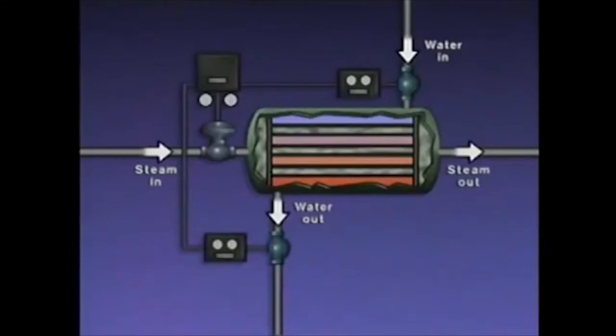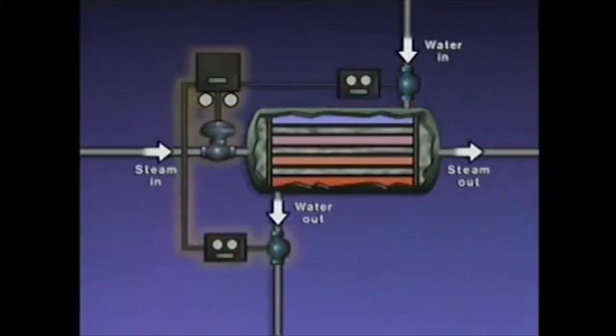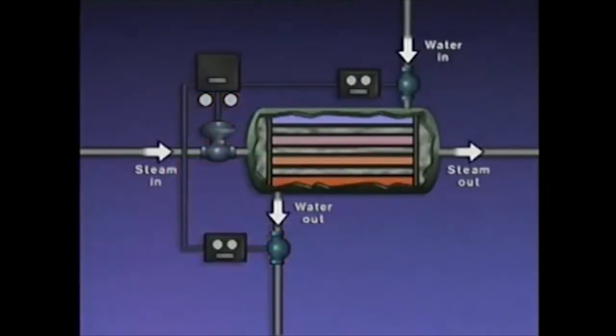This control system can be corrected by combining a feedback system into it, which results in a feedback and feed-forward control system. The feed-forward responds to changes in water inlet temperature, while the feedback responds to changes in the outlet water temperature, which are caused by the surrounding disturbances.